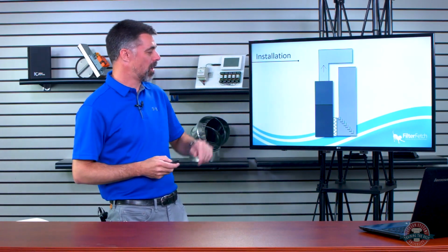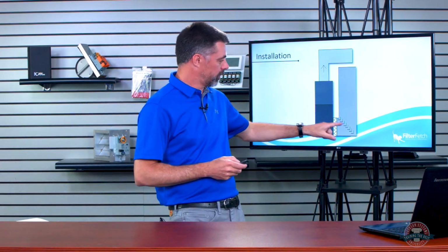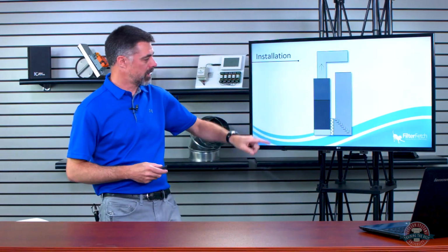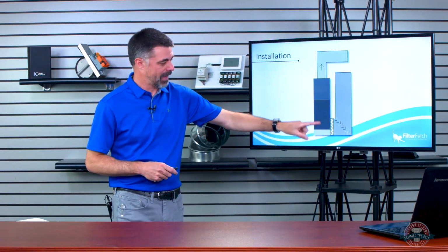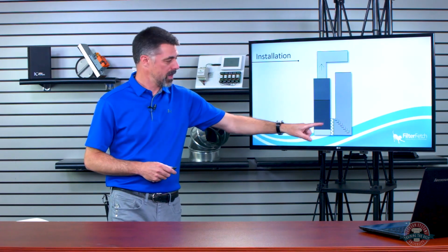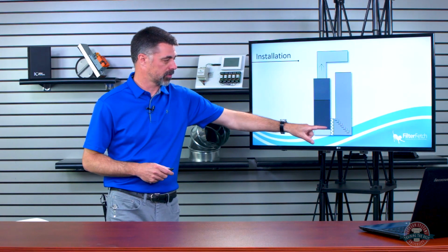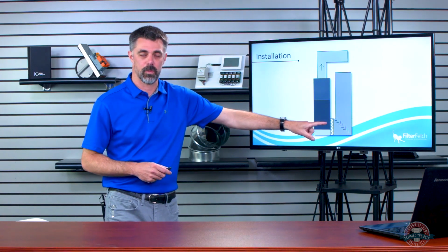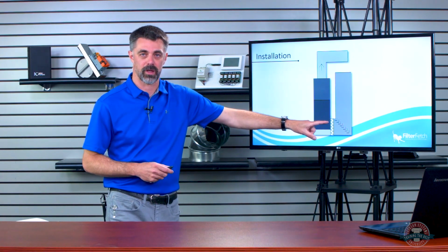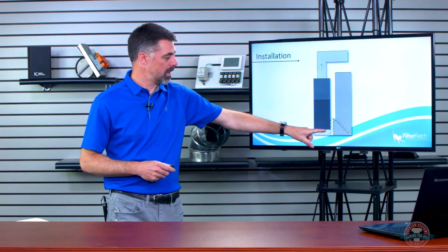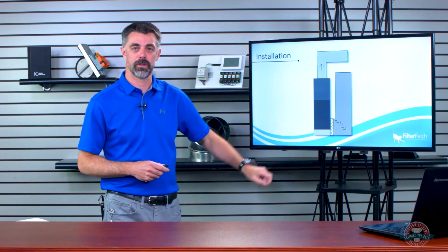All right, so on to the next thing. This is one option here. We can help with the turning vanes. Something else we can do, if we have a gas furnace in here, is we may need to expand this filter a little bit. So if we have a certain size opening, like a 16-inch high opening in the size of that furnace, which is pretty common, we may want to put a 20-inch tall filter on there.